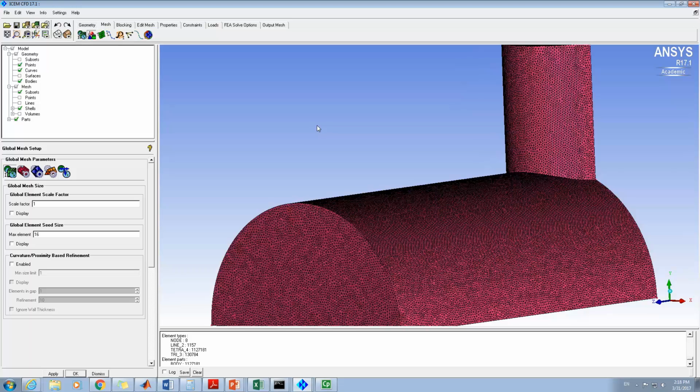When I say quality, that means the quality of the final CFD results. So that means to eventually have the same CFD result quality, we will need many more unstructured mesh elements than using the structured mesh.